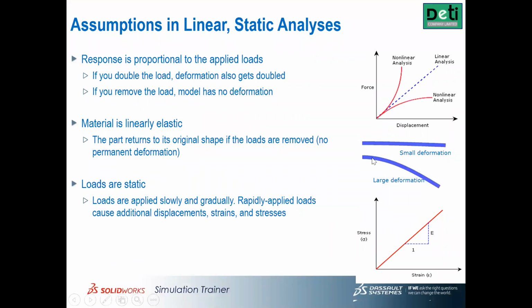So for our analysis, which is static analysis, in the engineering design we try to use the property of the material in the elasticity. Remember elasticity is a linear deformation, and that means when your assembly has deformed and has large deformations, it is really out of the elasticity.